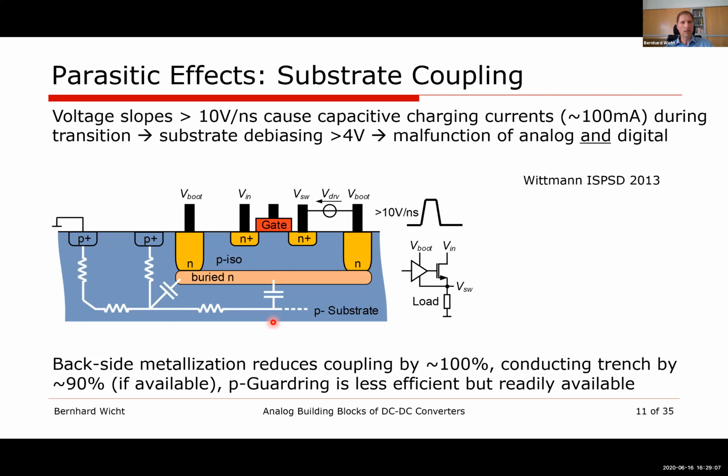I know there's also ongoing research on that for more than 20 years already. But we didn't use high power. We restrict ourselves to currents in the range of a few hundred milliamps for fully integrated DC-DC converters in SOI, and we didn't have any issue with self-heating yet.